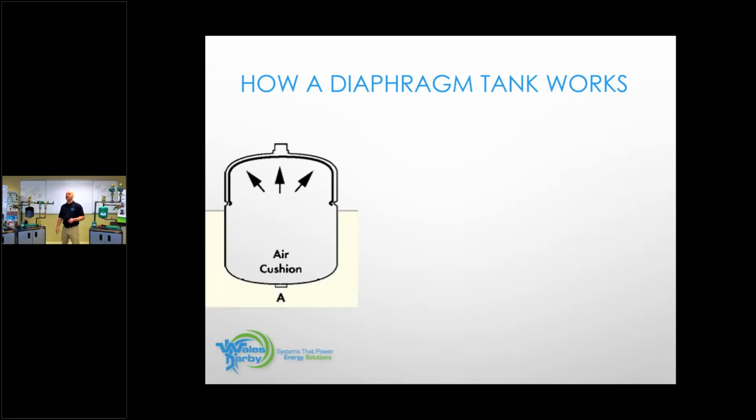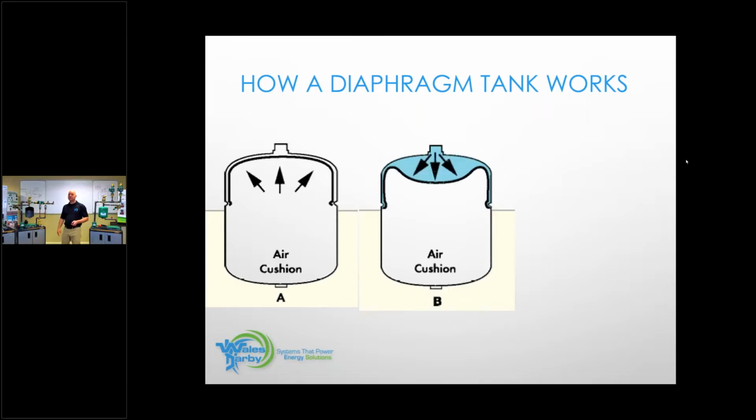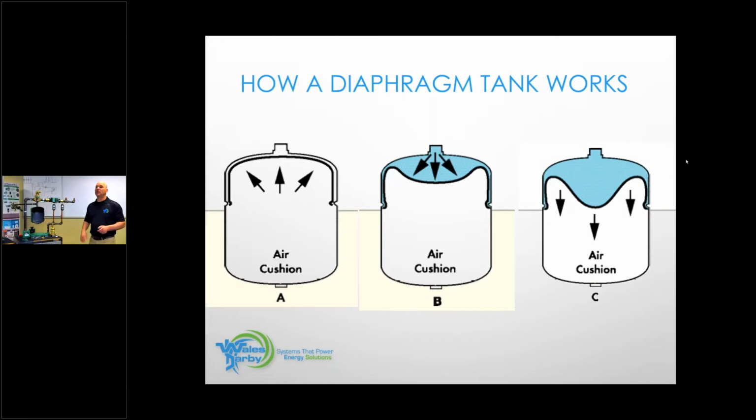Okay, so again, this is just a quick little showing of what it looks like coming out of the box. The rubber diaphragm will be pushed all the way up because we have air pressure here pushing against it. As we add the feed valve, we turn the water on to the boiler system. It'll push this little rubber diaphragm down a little bit and we'll equal out.